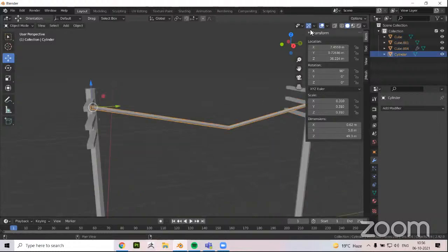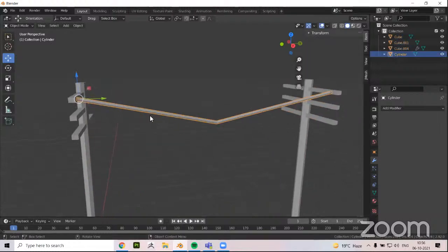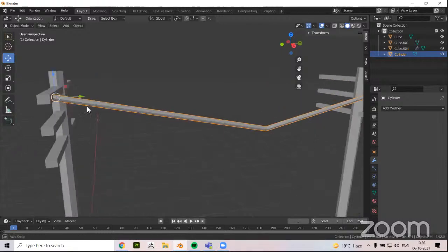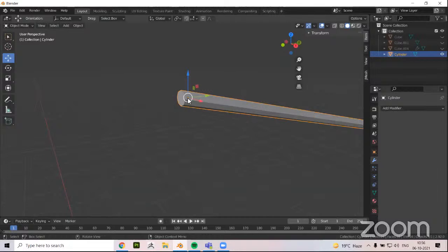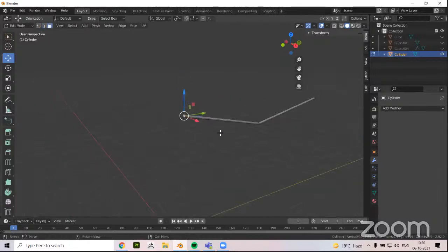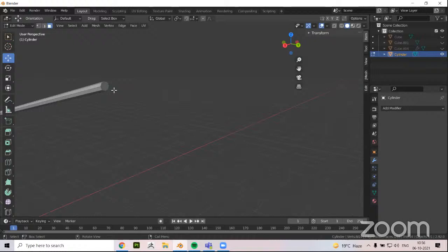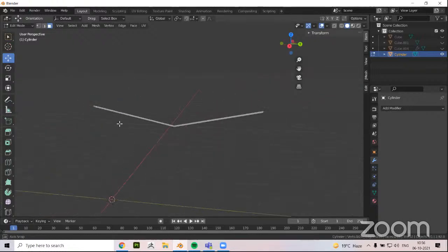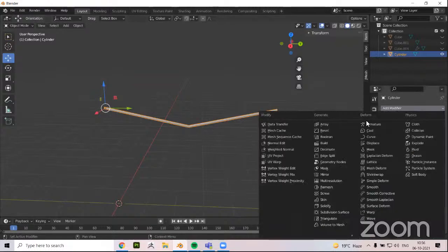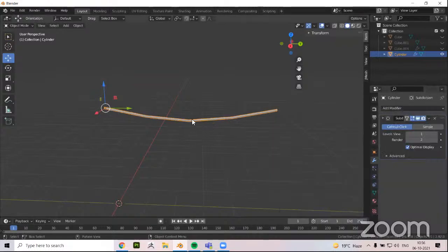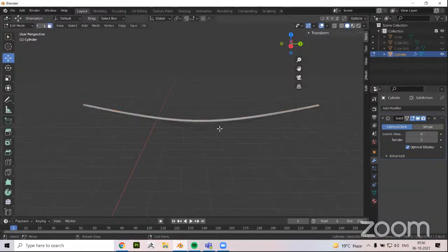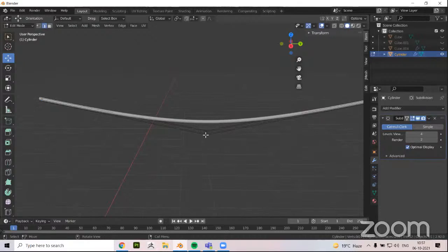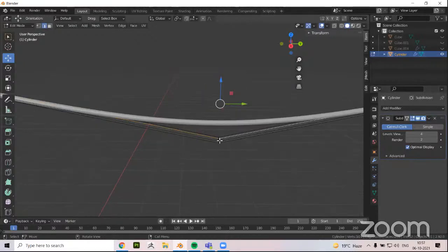we have this cylinder with a subdivision on it, but we can see one thing: the faces which are here won't be visible because they're inside our mesh. So we can just delete them. Okay, sorry, delete faces. And right now I showed you a tool called subsurface, right? The moment I hit subsurface, it'll automatically start to divide itself. And once I go to edit mode, I'll still have my original loop in between to have the controls.